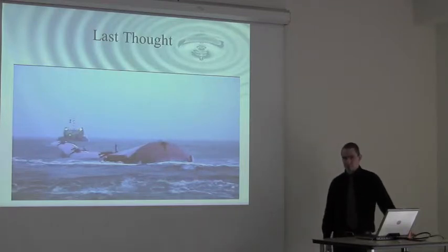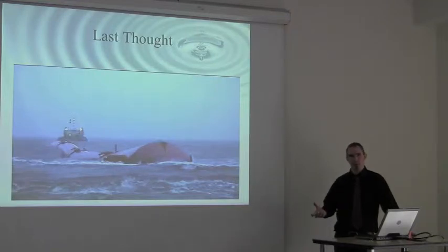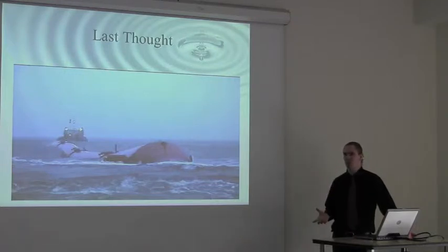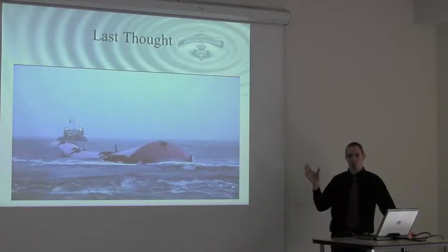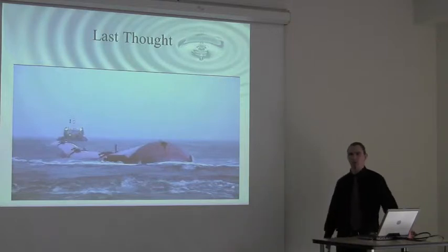In several cases, you mentioned there's obviously a turbulence effect in this case, but during any of your experiments, did you try to calculate what the Reynolds number is on the surface as a way of characterizing for future work the effect of the turbulence on the surface? No, I haven't. It just hasn't been done. Calculating the Reynolds number ends up being, I found, relatively challenging, because it's an oscillating body. So your actual fluid flow around it, the speed of fluid flow, changes as you move through the motion, so you can't apply steady flow theory to it. So I shied away and limited the scope of the project from that.